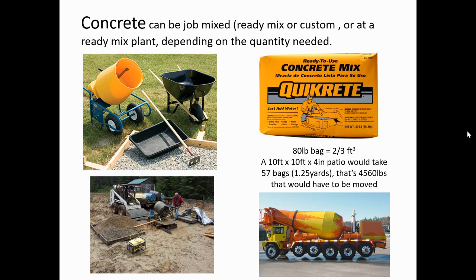If you're doing a bigger job, like a sidewalk or something, you could do this yourself. Or you can call up and get it all mixed and delivered in one of those big, huge concrete trucks. So this is going to be important to us. That bag of concrete, the ready mixed concrete, is an 80-pound bag. Well, I had to look it up. So how many cubic feet are in a bag? It is not even 1 cubic foot of concrete in that bag.